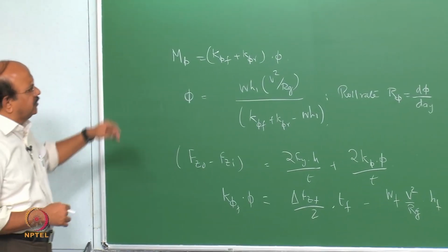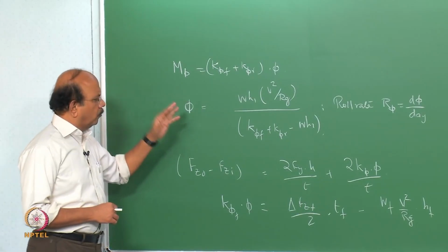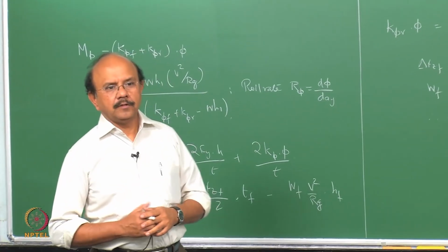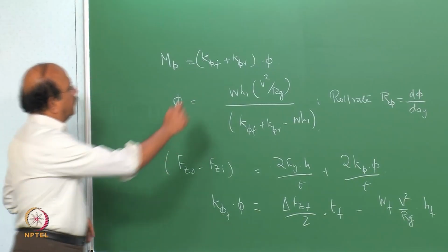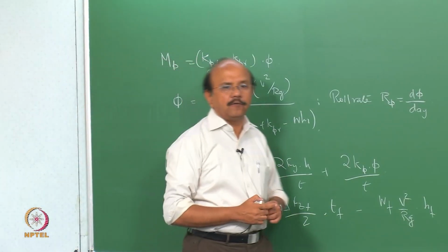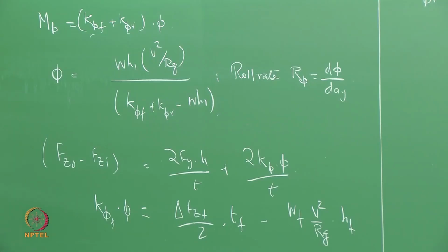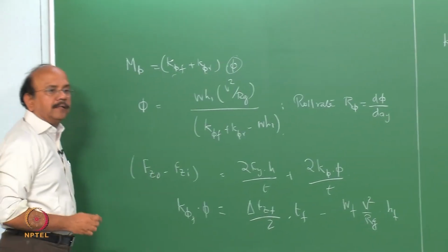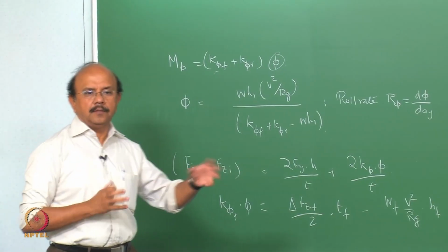This also gives a very good insight into what happens. I'm just going to recapitulate this. There's a small difference between what we have done and what, for example, the Gillespie book has, so let us be very clear on that. That's the front roll stiffness. Rear roll stiffness, you know what they are: half into Ks into S squared and so on. We said that if this were an independent suspension, then S is taken to be T, the track. Phi is the roll. Note that the body being stiff, it rolls through only one angle. There is no twist, there's no torsional stiffness.